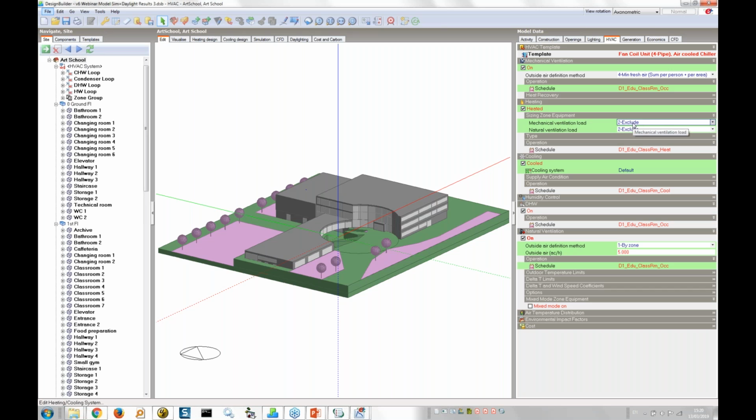And that enables you to set the relevant sizing options, such as including or excluding heat recovery. Note the green text indicating that these inputs are only used for heating design calculations. You should ensure that they are correctly set up as part of the HVAC system before running these calculations.